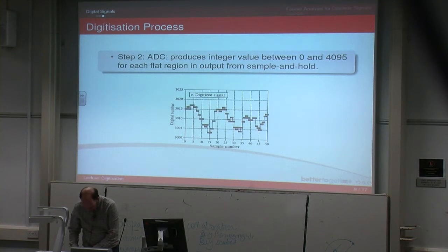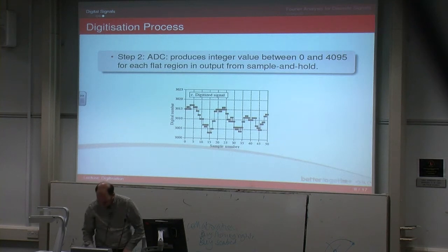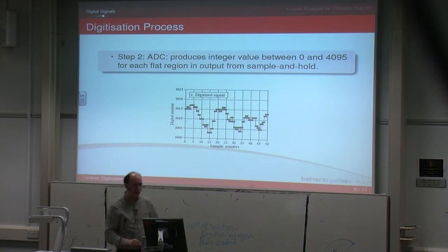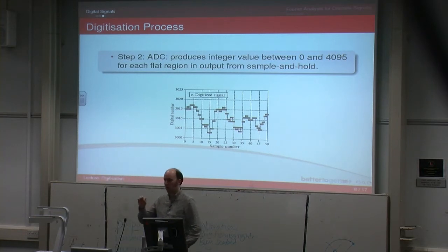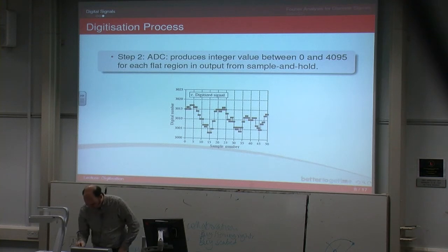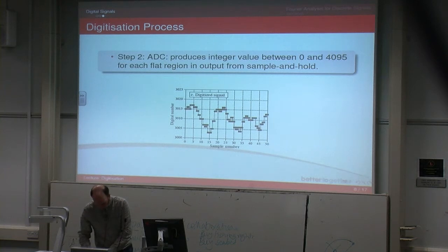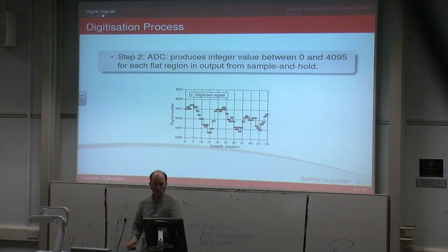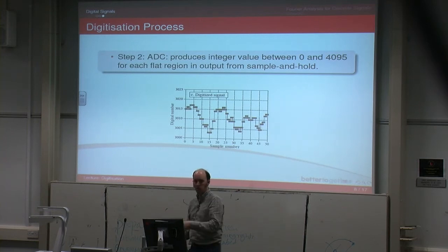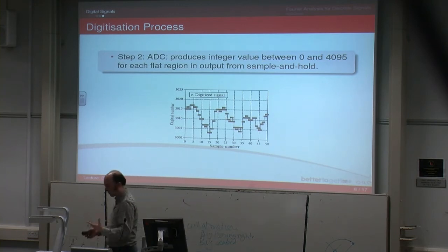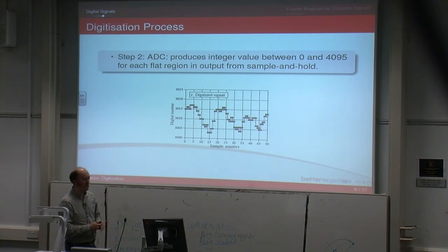Like I said, this is at the bottom of page 149, if you've got a voltage of 2.56000 and another point you've got a voltage of 2.56001, they're both going to take the value of 2560. Okay. So although the voltage is different in the analog sense, it's actually going to be the same when you've got the digital signal. So that's the whole process to convert an analog signal into a digital signal. Once you've got this data, the computer can read and write it, you can do analysis to it, all that sort of stuff, and that's how you deal with the digital signal.